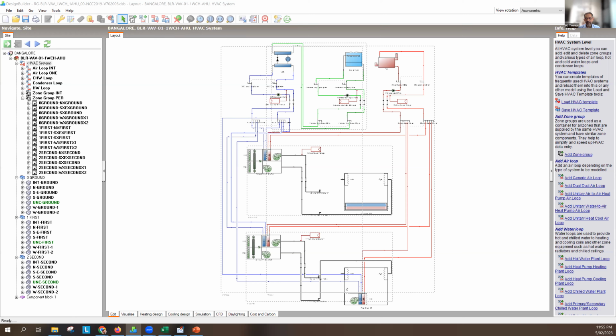One is, if you're asking me, are we modeling the refrigerant circuit? The answer is no. We are modeling a correlation of the compressor's map. So basically we are saying, okay, if these are the conditions, then the compressor will use this much electricity, and that's what we are modeling. Number two is, does a chiller use refrigerant? Yes, absolutely. But you don't see it because it's all contained within the chiller.